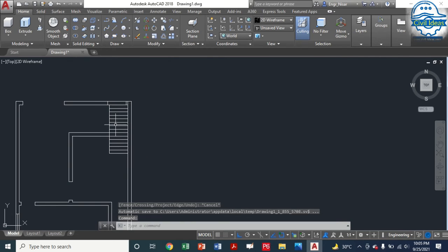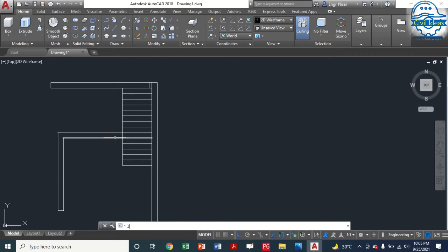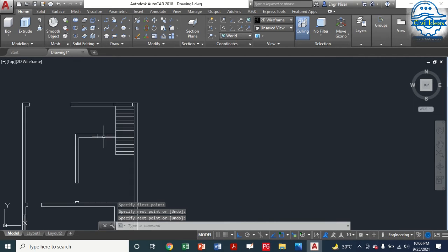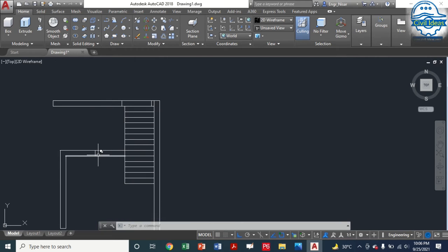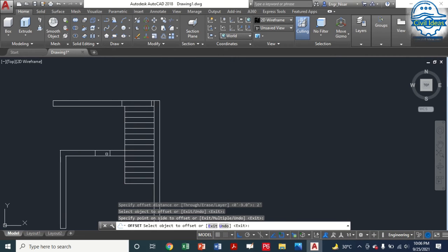Now you can provide a washroom under these stairs for this room. So this is the main benefit of this type of staircase, and also the access directly to the first floor from outside. Now enter. You can provide a door. You can also provide a window here or here, but it's the front side, so you can provide it here. Offset equal to 2 feet. You can provide 3 feet also. You check it, 2.5 feet. Offset equal to 2.5 feet.